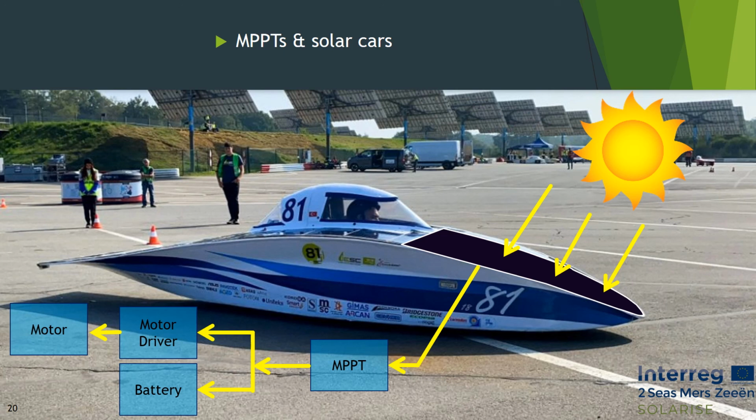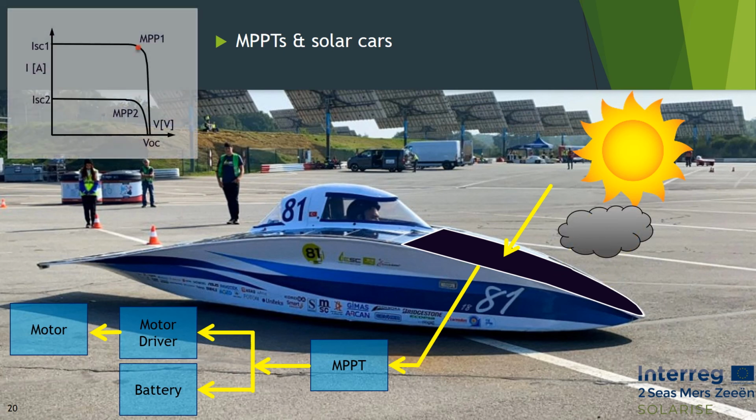The instantaneous energy need of the vehicle and the changing solar irradiation determine whether the energy generation should be used to travel or to charge the battery. These cars are highly efficient vehicles which can reach up to 150 km per hour with nothing more than a 2.5 kW hub motor. In these cars, MPPTs are highly crucial parts.